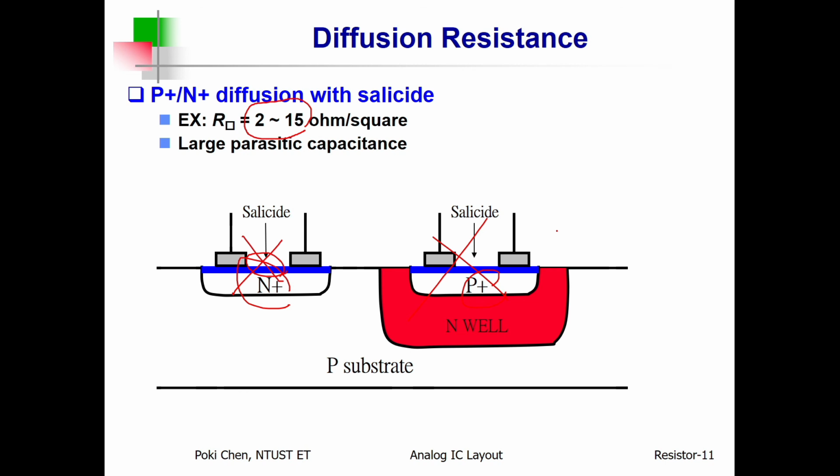So you cannot please everybody, right? TSMC or UMC would like to speed up the operation of our main device, I mean MOSFET. They help us to have such kind of metallic compound over the surface of our source, drain, and gate. However, if you would like to use such kind of area for resistor, you will complain, hey guys, don't help me have such kind of silicidation.